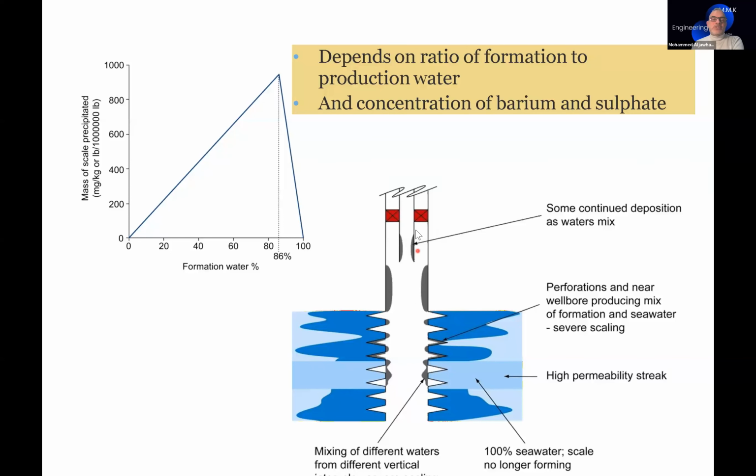maybe inside the wellbore itself or the surface, or maybe inside the tubing, the production tubing. So we need to investigate when we have any kind of identification that there is a scale inside our system or inside our well, and how to remove this scale. What are the scale parameters? I mean the chemistry of this scale, and what is the best action we need to take? What is the best solvent, or mechanical or operational action, to remove this scale?